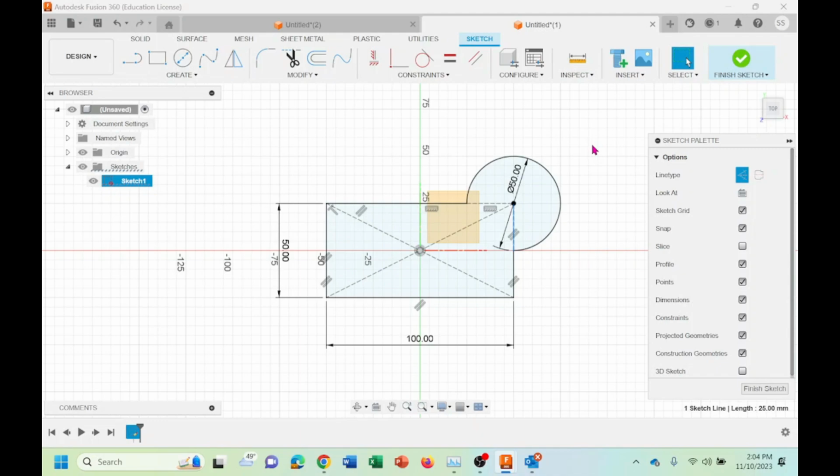So again, this is really upfront, you don't know whenever you use the tools which tools the software is going to work with or not. It is based off the experience that you have. If you have more design experience, you slowly get that. So for this case, you see you put these two as a construction. You are able to trim the other part and still be fully constrained. Which just tells me I'm good for now.